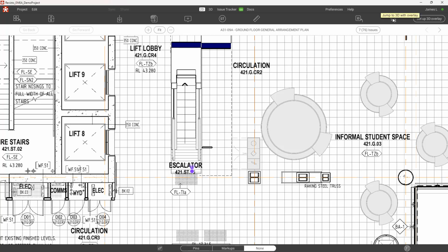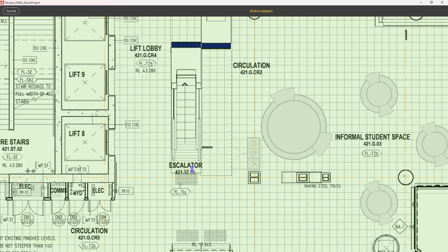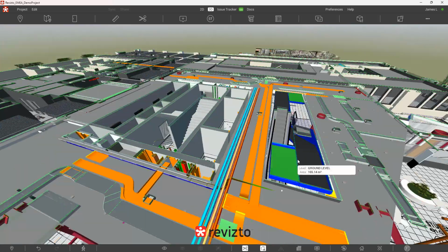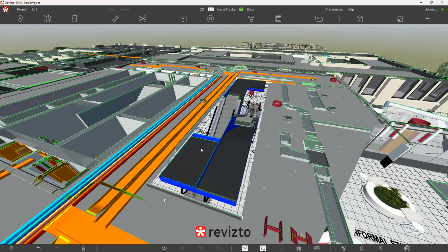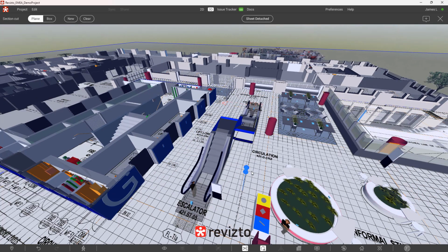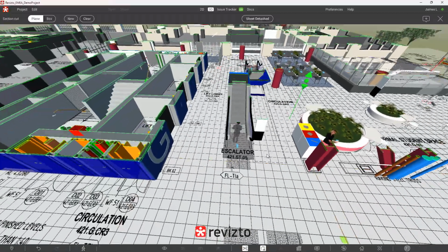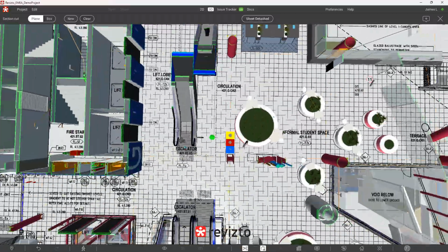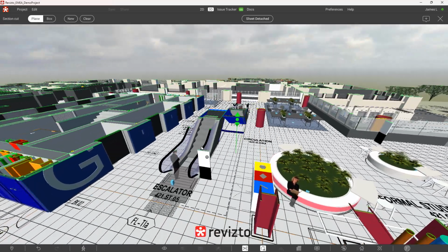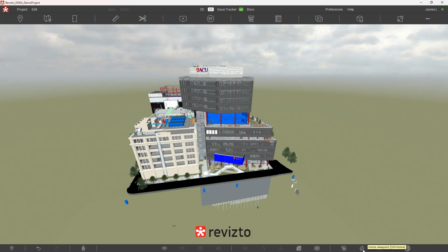Clicking on Jump to 3D with an overlay allows us to again pick a point, this time giving us the orientation of the 2D drawing overlaid on top of the building. We can pull the section cut up or down to again orientate the drawing to see exactly how we want it to be within the 2D and 3D space combined. Clicking on the home button will reset the view back to normal.